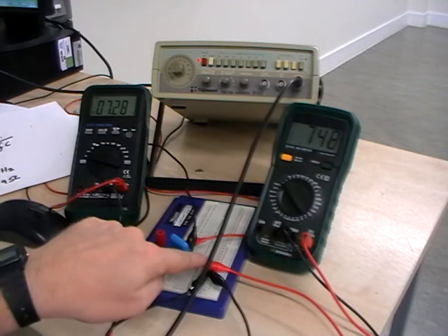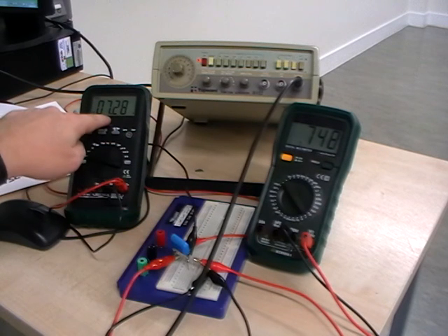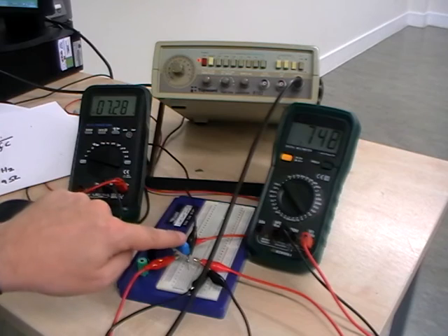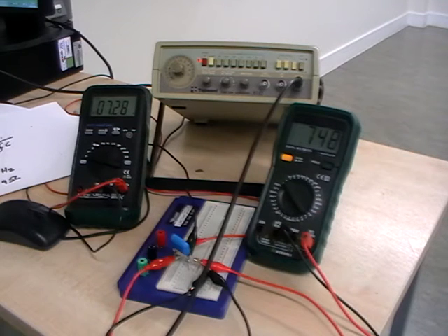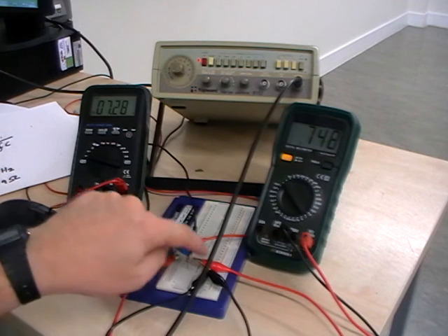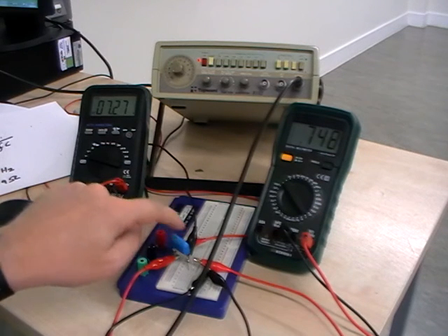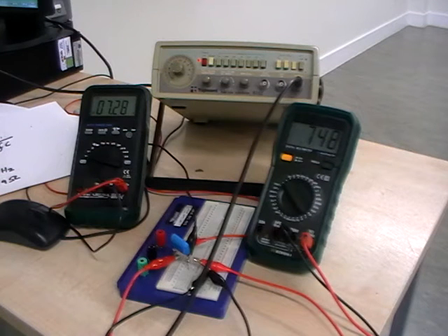So we've got 150 ohms here. And the reactance, when we look, we've got 7.28 volts dropped across our capacitor, and we've got 700 millivolts dropped across our resistor. So when we look at the difference now, it's a factor of 10. So we know that that one is 150 ohms. So therefore, the reactance across our capacitor must be 1.5 kilo ohms. Yeah, so 1,500 ohms. So we've gone down from about 15,000 ohms to about 1,500 ohms by just increasing the frequency from about 10 hertz or 12 hertz to 100 hertz.